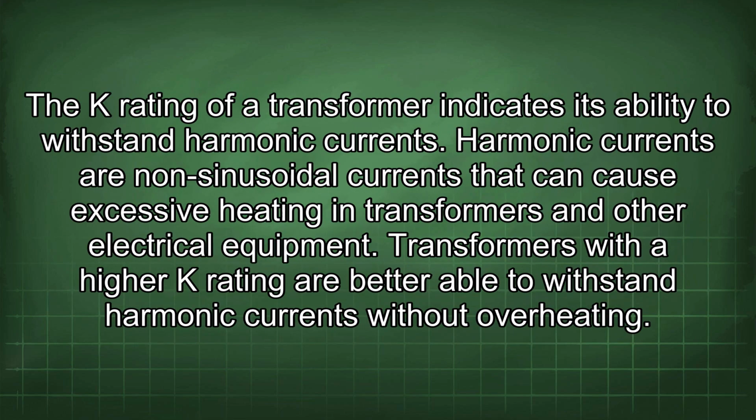The K rating of a transformer indicates its ability to withstand harmonic currents. Harmonic currents are non-sinusoidal currents that can cause excessive heating in transformers and other electrical equipment. Transformers with a higher K rating are better able to withstand harmonic currents without overheating.